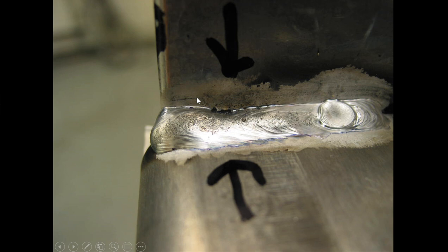A quick story, when I was a younger lad, my journeyman used to paint a little welded part, and he'd say, I want you to grind that weld down, and he'd paint it so he could see if I touched the heat affected zones. It's not a bad little way of testing it, and it's pretty easy to see if you get it bad as well. So getting that out of there will take a fair amount of skill with a die grinder. It might even take a different type of die grinder than you have available to you. But you can't get that hot and fix it is one of my main points here.